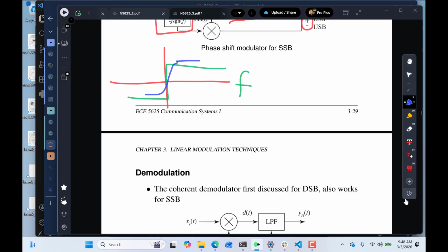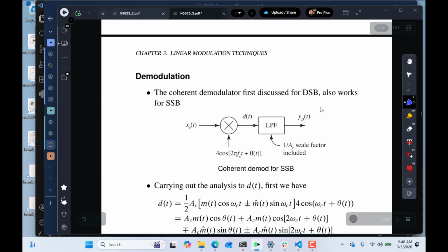So, okay, let's get back into looking at some more single sideband and demodulation of it, and then we'll do some demos, and eventually we'll wind around and get down to the exam review. So how do we demodulate single sideband? We can use fully coherent demodulation, just like we did with double sideband, which is what the telephone company did. They used a fully coherent demodulator. They just simply were doing it to save bandwidth, to put twice as many audio channels on it.